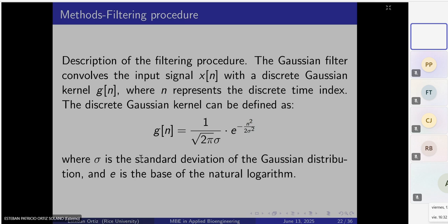People know how you can use this equation. Right now you can change it, but it's important that you at least understand the general way you can choose one filter instead of another. In this specific case, the Gaussian filter is the most common one when you're doing mechanical testing for tissues. I did this in Python, so you can just import the library in Python. And the filter is applied to the signal of the mechanical tester.